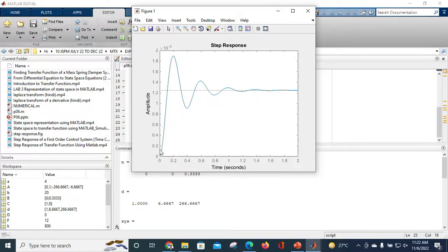In the step response, you should be able to tell that initially there is a more sinusoidal curve with more amplitude, meaning more oscillations. The rise time is less, with sudden oscillation, then the oscillations are damped because we have used a damping system here. Remember, it is a spring mass damper system. Because of the spring, oscillations are there, but we have used the damper, hence the amplitude is reducing. The damper comes into the picture for this part, and after that the system performs normal operation, a smooth curve. This much you should know.